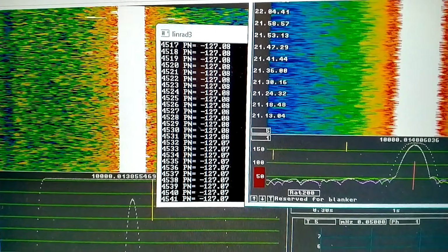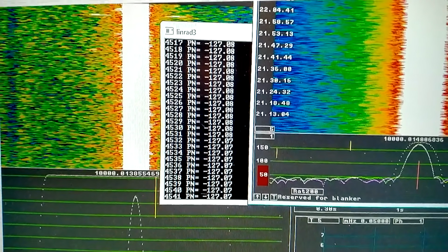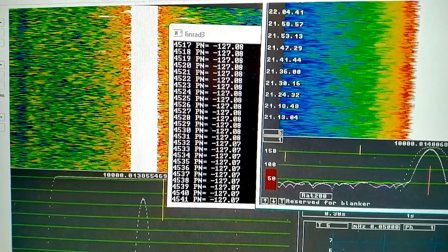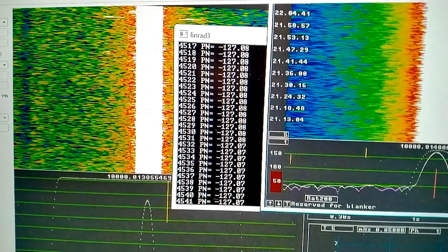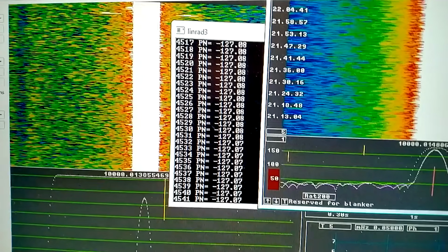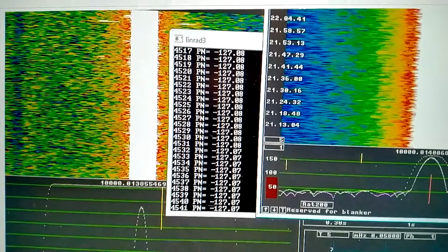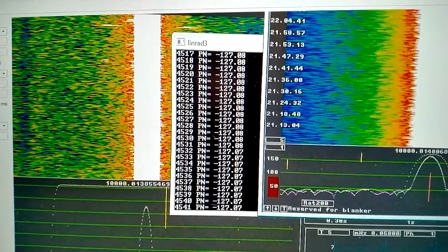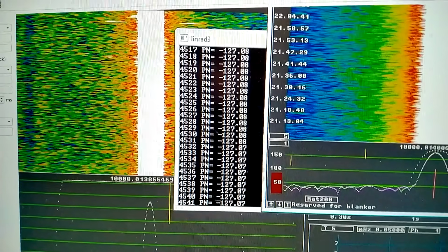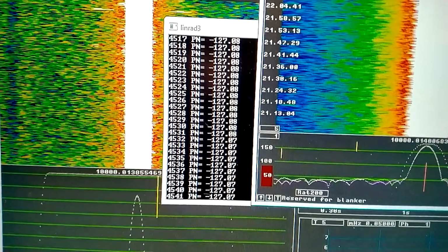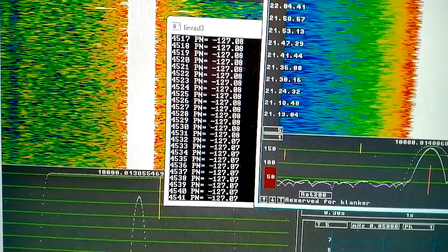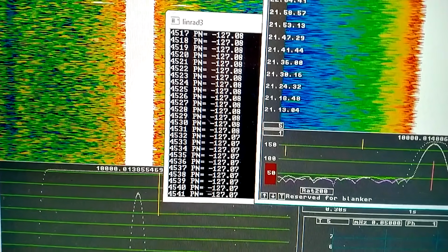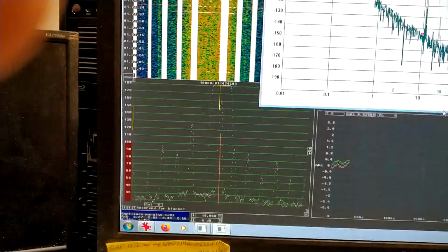I spent quite some time trying to get back the performance for average noise at -130. But I failed, and I don't want to continue to rebuild everything, because performance is not bad even at this level. I want to continue, for the main purpose of this video, to get 2 reference oscillators, both of them locked to the shifted rubidium source.